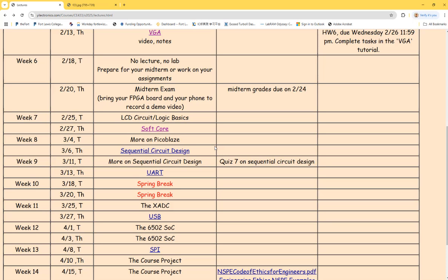So the two methods you can use: first, you can use FPGAs, because all the pins on FPGAs you can totally assign to different purposes. They are all free pins. You can assign 64, even 128 pins on one direction. Or you can do a totally custom ASIC like VLSI, but that costs a lot of money, usually $1 million for one design. It's very difficult. If it's just a very small contract, FPGAs will probably be the best option.